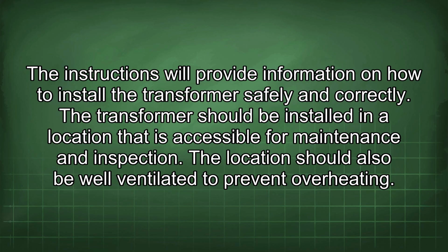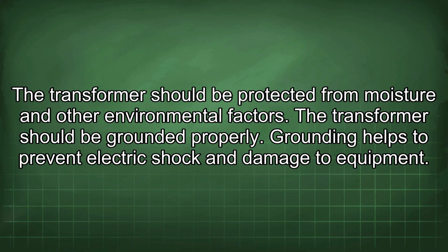The instructions will provide information on how to install the transformer safely and correctly. The transformer should be installed in a location that is accessible for maintenance and inspection. The location should also be well ventilated to prevent overheating. The transformer should be protected from moisture and other environmental factors.